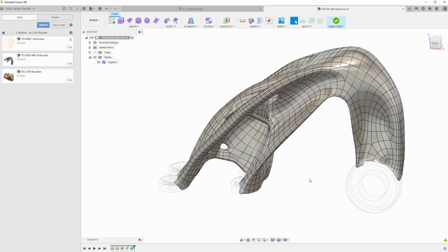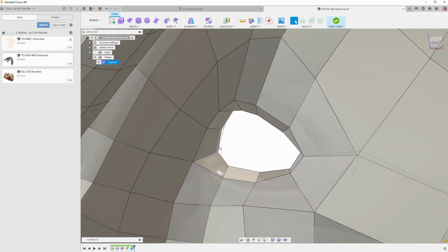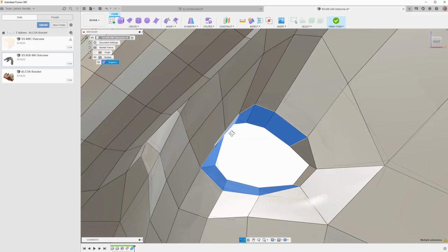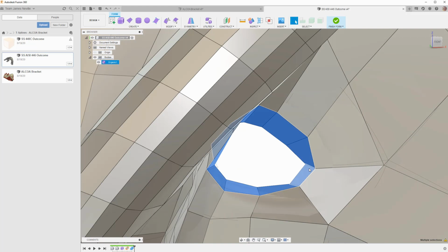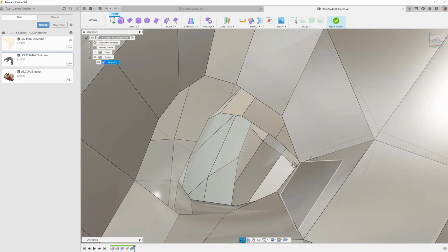This model's really smooth. I mean, it was smooth to begin with, but now it's really smooth. Let's talk about hole removal next. Let's go back into the box view mode. So if you want to remove this hole, you can come in here and manually delete stuff if you want. Certainly a possibility. Hit the delete button. It'll actually just remove that. That's now an open face.